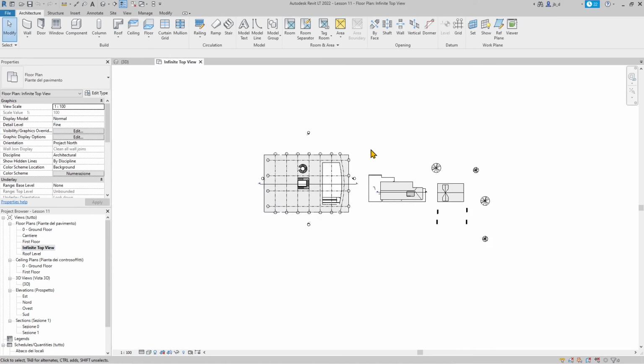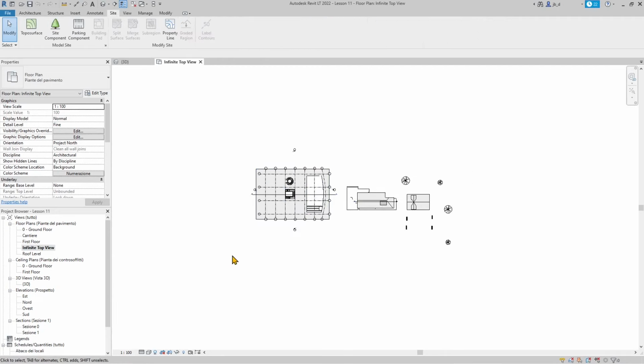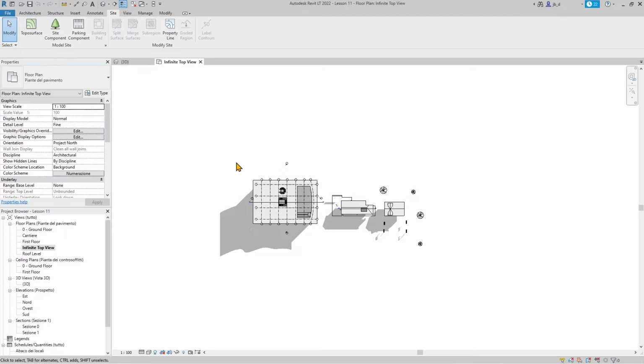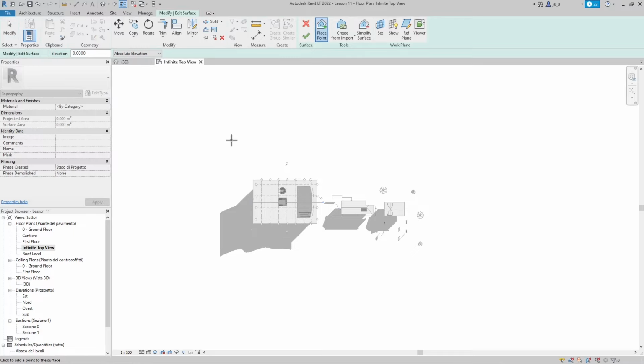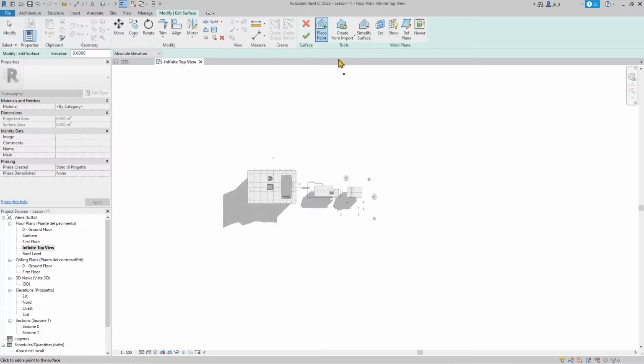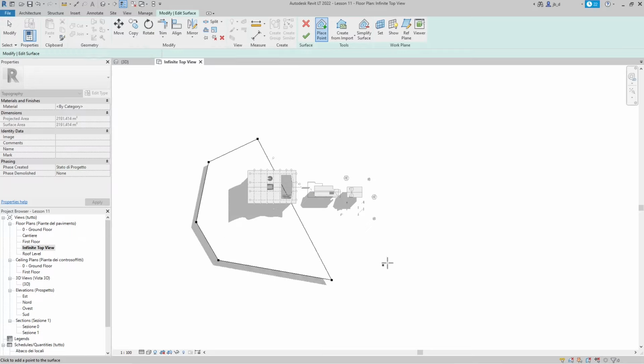This will help us to create the site and the Toposurface. So let's start with the Toposurface. I'm gonna click here, and you can see that we can start to place points. Now we have three options when we need to create Toposurfaces. We can create them by placing points just like that randomly, and this is our first level curve. This is how this is called.